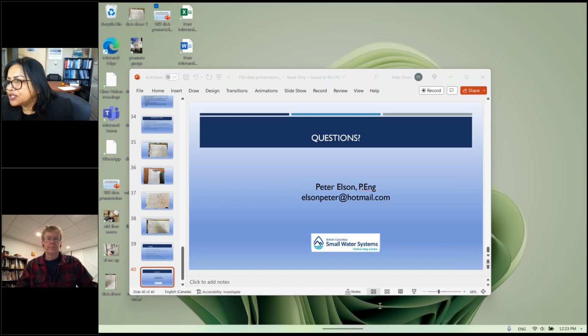Mark, maybe we can get back to you on that question. If you give us your email, we'll make sure that we can get back to you. But usually your contact time is set up during the design of your water treatment and the design of your clear well system. And then if you make any changes, you do have to recalculate your CT. We can definitely send you a link on how to calculate that CT. Just email us at the Online Help Center and we'll make sure we get back to you.